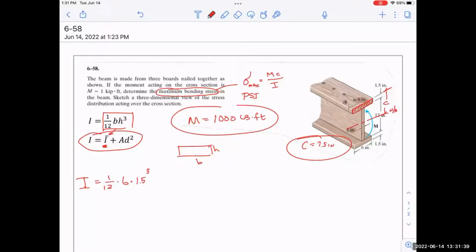That's because this material right here is only like a couple centimeters away from the top. And so it isn't hard to get that to bend. But if it's way up here, does it make sense? It has to get crushed way more. And if it's wood, it's going to say, I don't want to do that. It's not going to want to bend. You want stuff to be tall.